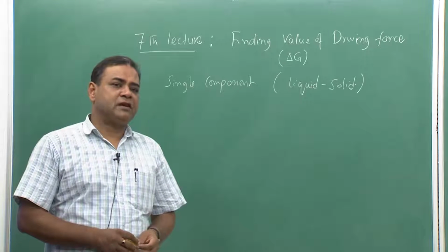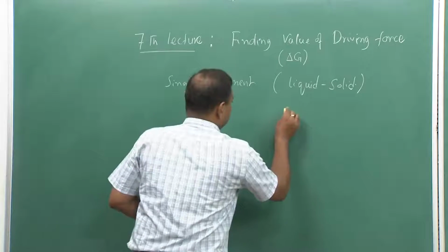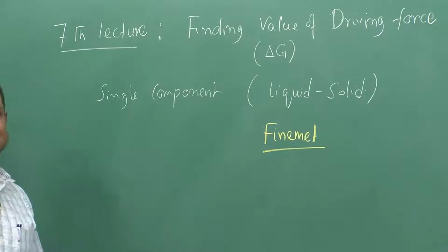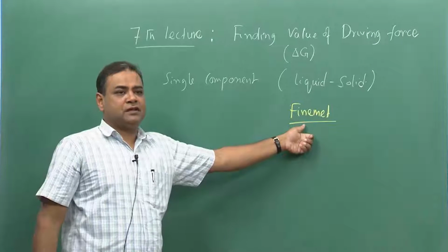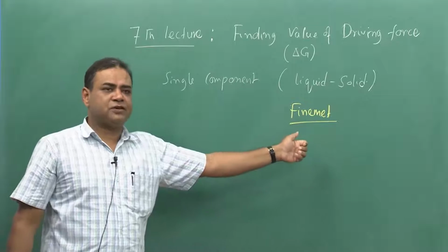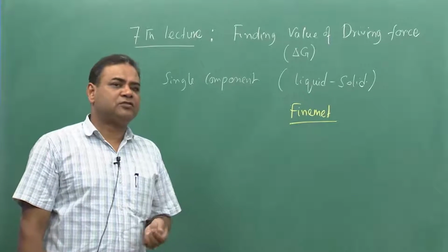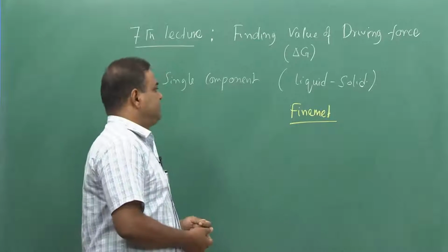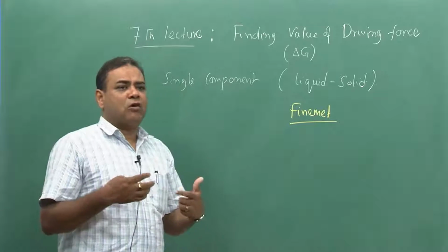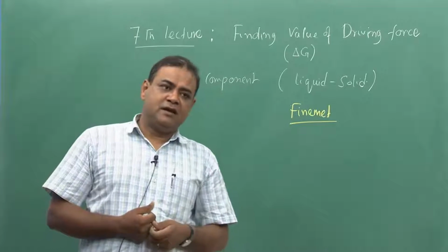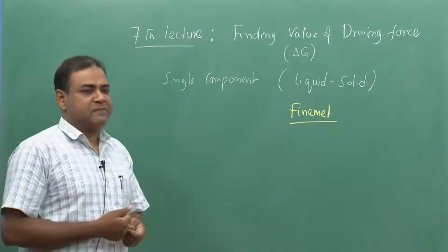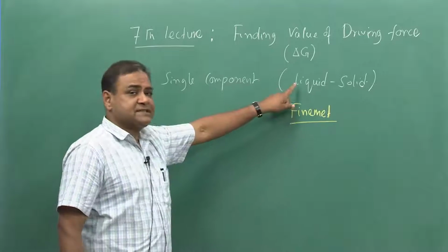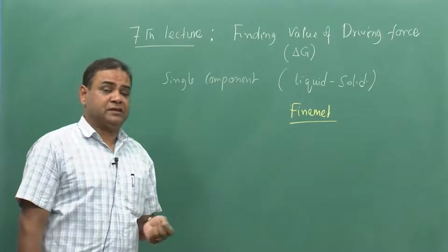One of the famous metallic glasses is Finemet, an iron based metallic glass which has fantastic soft magnetic properties. There also we try to get a glass in solid form, and later modify its structure by crystallizing, to improve its soft magnetic response. So in those cases this particular transformation would be very critical.